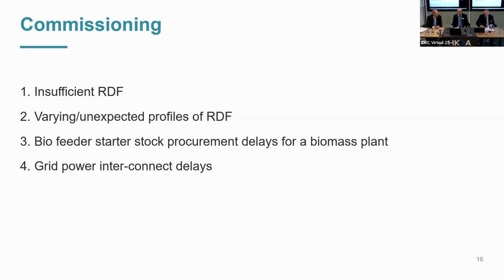So there's typical examples. And finally, in commissioning, if you have a combined system where you're processing domestic waste, and then you're using that as a refuse-derived fuel, you have to have sufficient volume of that material to ensure, if you're, for example, commissioning a gasification plant, that you have sufficient volume, and that volume can be processed. It's particularly key, I found, on some of the projects about food waste. You need large volumes or tonnage of food waste to start your biomass process.